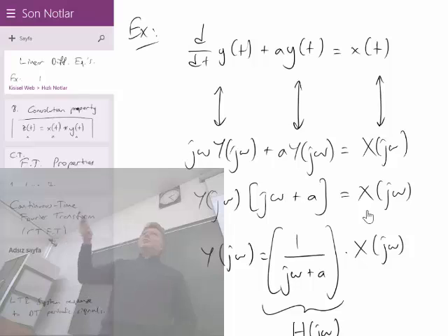Or, let's now reverse the question. I can give you a second order differential equation. From there you take the Fourier transform of both sides of the equation, and then you will come up with Y(jω) divided by X(jω) with two such expressions, probably. And those two things will correspond to two exponential terms in an impulse response.